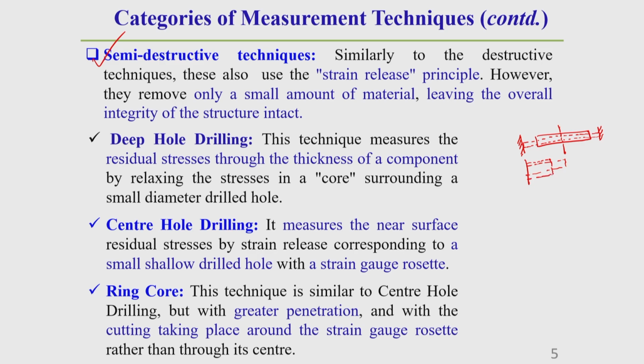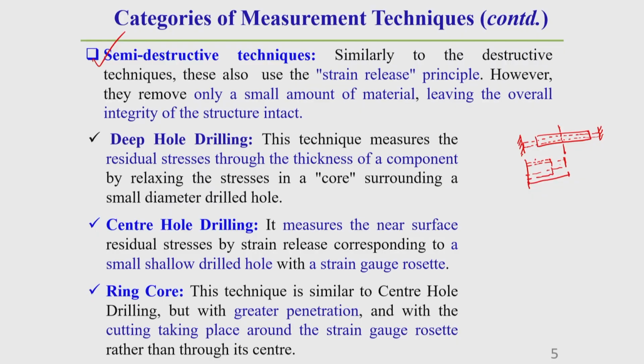Initially this cut length was this, due to elastic strain. Once we cut through this section, it will return back to this final length, that is the final length LF. Once we cut this, it is released and shortened if it was elongated. Now, if it is compressive due to this locked-in condition, then if we cut that position, it will elongate.